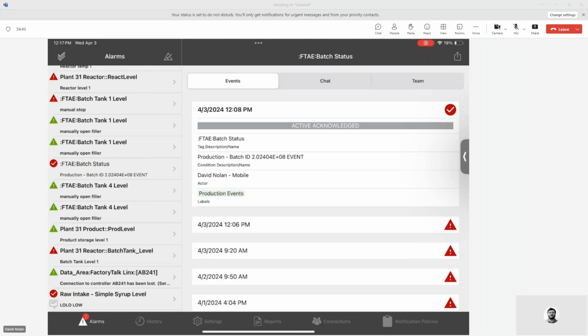I think you probably asked that before I covered it, but yes, you absolutely can. If you have multiple Win911 systems, maybe it's a FactoryTalk system and they're all in different directories, each one of those Win911 systems can be configured with the same email address.